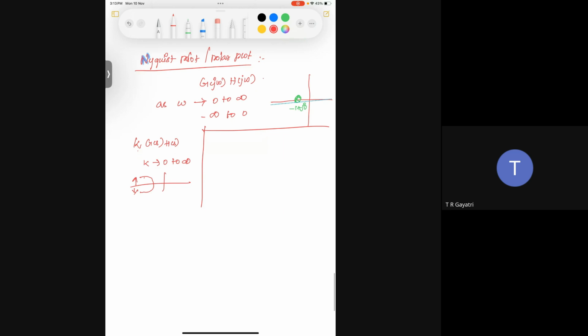So in Nyquist plot, how will we design the stability? That's the important point here. So think of minus 1 as a center of attraction, and if the path loops around minus 1 in a certain way, the closed loop system becomes stable. The certain way is defined as Z is equal to P plus N, where P is your open loop poles, N is the number of times your Nyquist plot encircles minus 1 plus j0 in counterclockwise, or anti-clockwise.